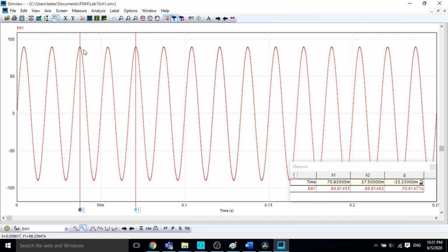And that's not a good thing, because it actually should have detected some of the peaks that were near to it. We first identify the peak to which we want to move our cursor. And first, we move cursor number 1 next to that peak. Let's say this is the peak I want to put cursor number 2 on. I move cursor number 1 to the peak before it.